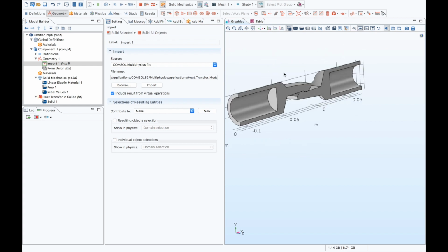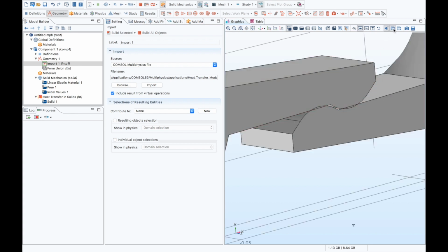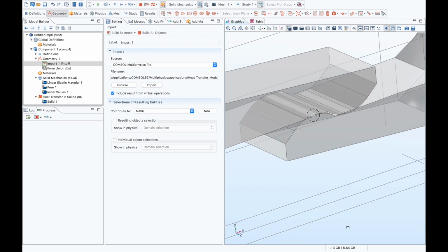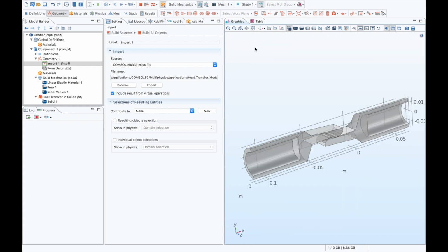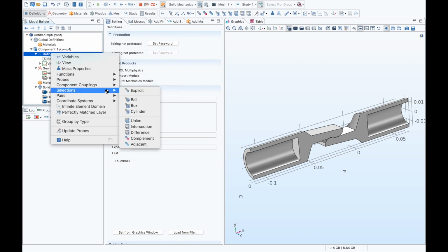As explained previously, here in the middle they are in an initial overlap. So here these 2 parts overlap, so it will give us a very nice initial contact pressure between the 2 surfaces. So first let's define the contact pair for the structural analysis.